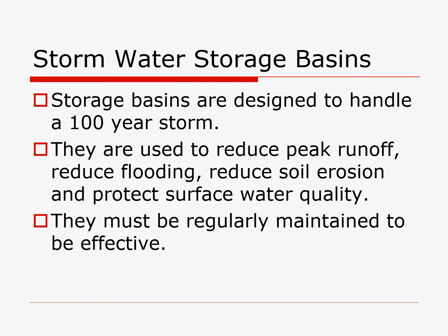Now, because that drops out, these are designed to be a certain volume so that they hold the amount of water that is needed during a storm. They have to regularly be maintained because those particles that fall out will reduce over time the volume of that basin. So that's why they have to regularly be maintained.